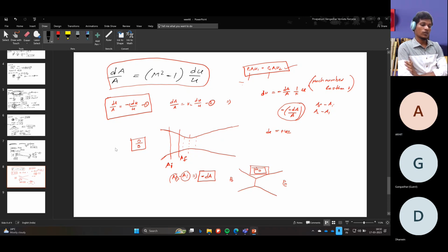Yes, there are no moving parts in the ramjet or the scramjet engine, but you need to see that the definition of the ramjet and the scramjet will give you the understanding of how they are controlling the velocity. Suppose you are taking a ramjet, the flight itself needs to run at supersonic speeds. Let me draw for you.